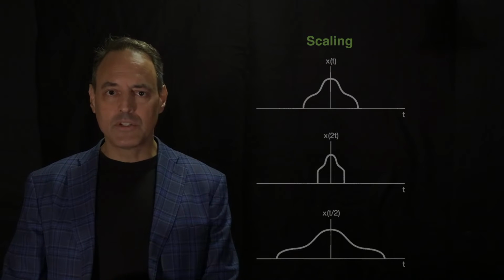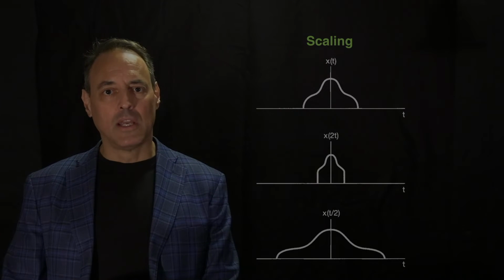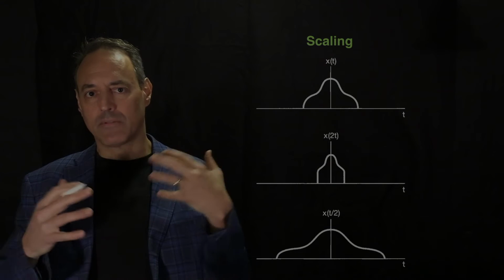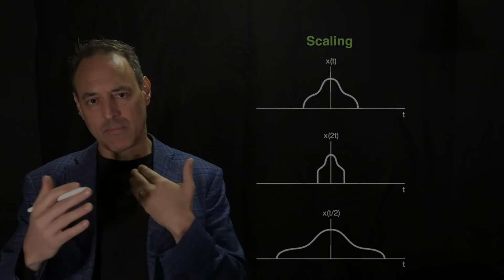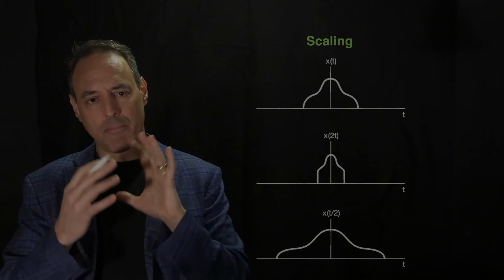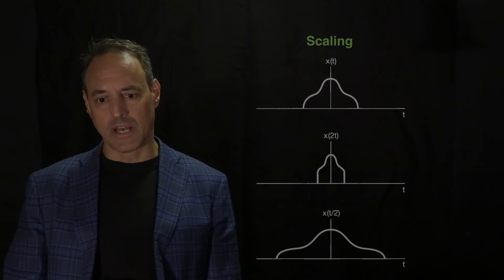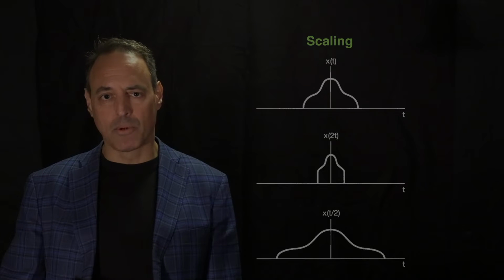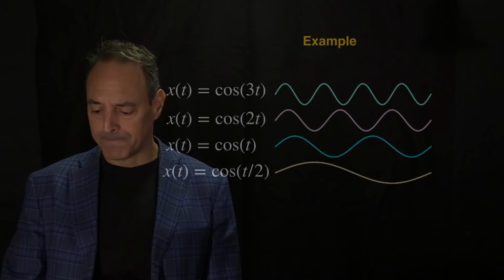And there are various reasons why we might want to do all of this. It could turn out that what we want to do is, again, synchronize different sensor measurements all to be of the same time, whereas if they have different measurement rates, you want to make sure to scale them all to be synchronous together. So scaling is a very important operation to go along with time shifting.